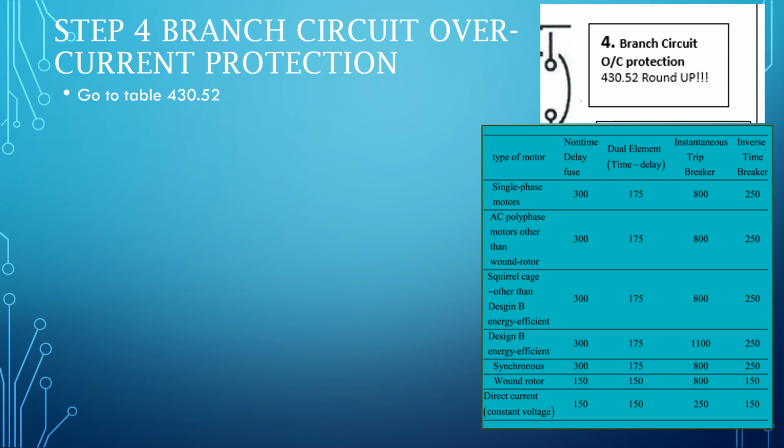That is not the case for motors. When we talk about motors, because of that high inrush current, especially at the home panel, if we just have an instantaneous trip breaker, you could have an inrush current on a 20 amp motor that's going to be 60 or 70 amps. We're going to want to make sure that breaker isn't going to trip every time you start the conveyor line.